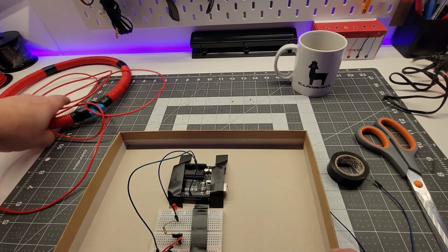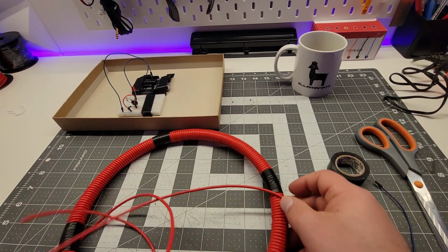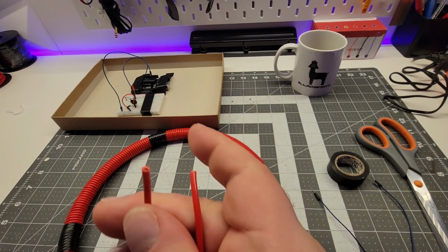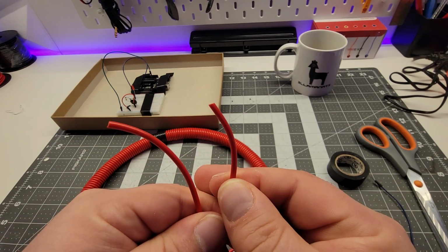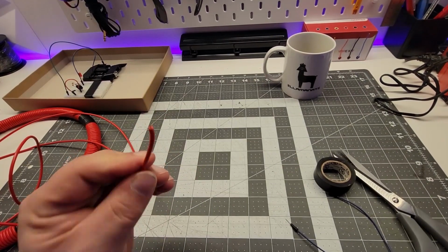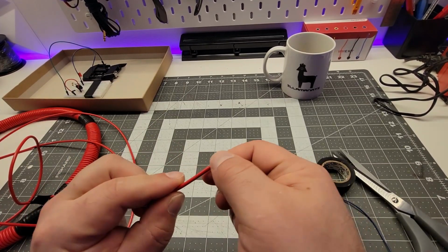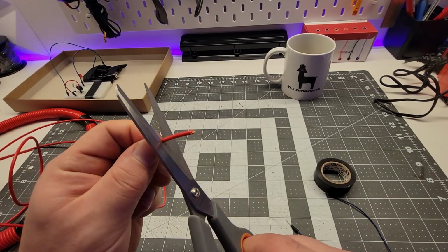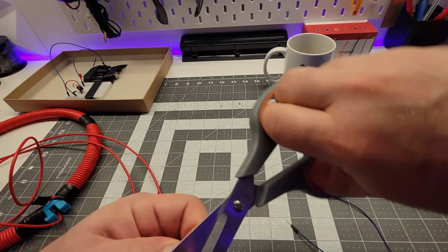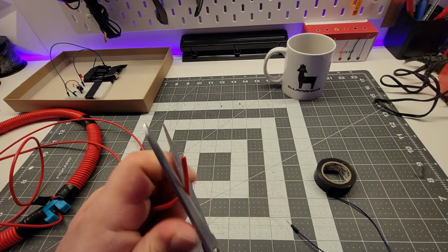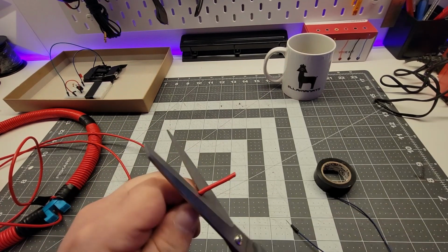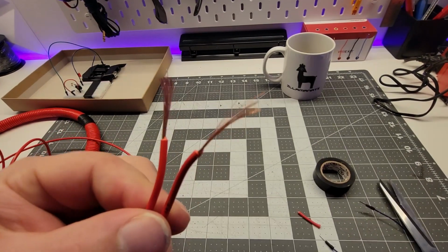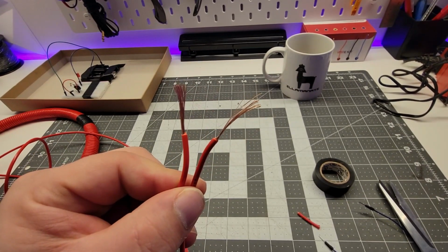Now, to start out, we just take the circuit and put it aside, and we want to find the two leads that come off of our coil, the end of the lead wires. We're just going to strip the insulation from the end of these leads, and you're going to take about 1.5 inches and put it in your scissors, and be very careful here, and just score the exterior portion of that until you can strip that right off. See how that worked? All right, now we have both of those ends stripped.